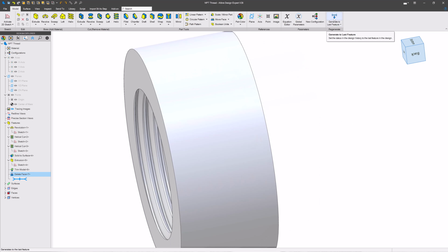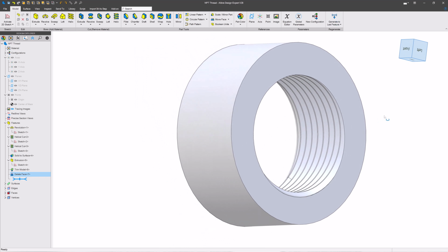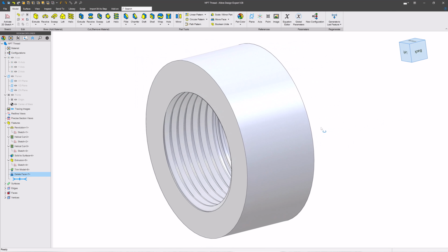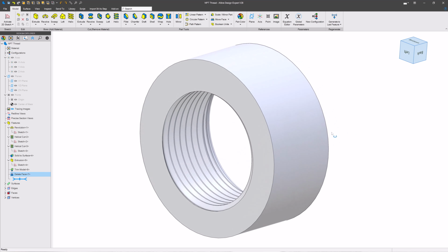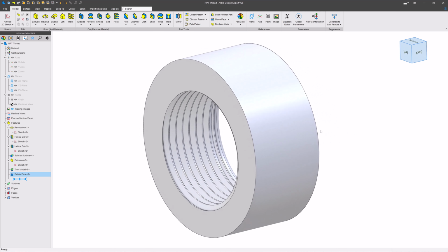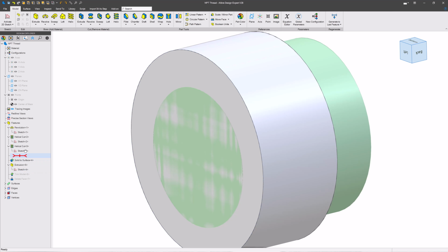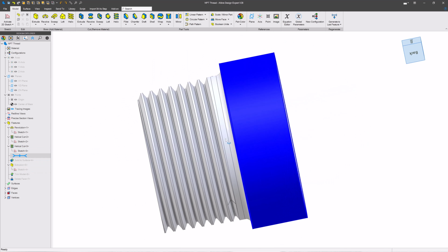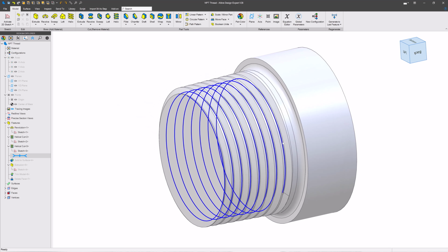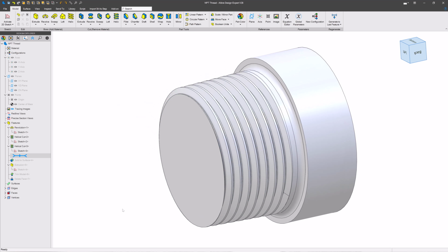Let's also cover how to instantly make the other side, an internal or external thread. We'll be working in nominal today. Nominal should be okay for 3D printing because 3D printing is pretty forgiving when it comes to things like this. And when we make nominal, it makes these kinds of changes very, very easy. And making nominal instead of production NPT threads makes it a magnitude simpler as well. So we'll cover all these things.